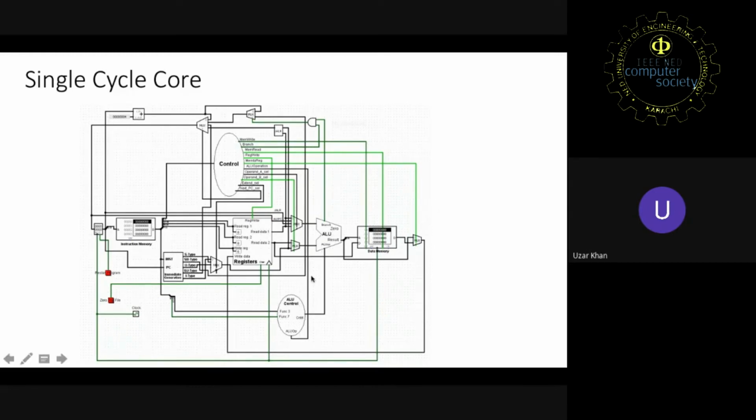Now moving towards ALU. ALU basically performs different operations depending upon the instruction we have. If we have an add instruction or subtract instruction from instruction memory, then it will compute the result, and the result will be marked in ALU result output. But if we have any branch instruction and branch gets true, then ALU result output branch would get high.